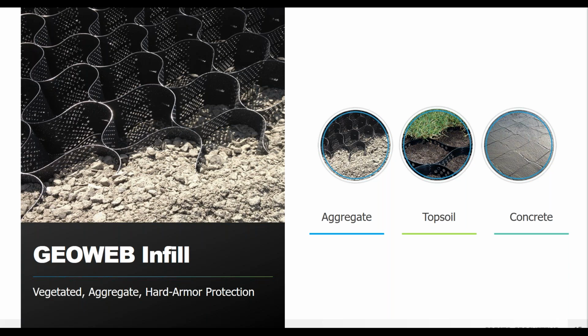Using those salvaged stone or sand materials can save a lot of money in material and hauling costs if you are in a remote location and it would be expensive to truck something in. Another option is to actually eliminate or significantly reduce the fines content of an aggregate blend.